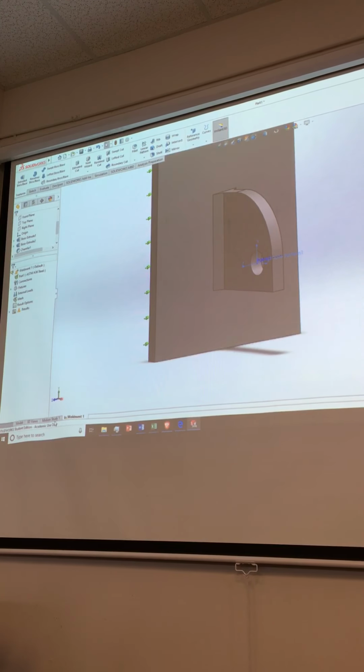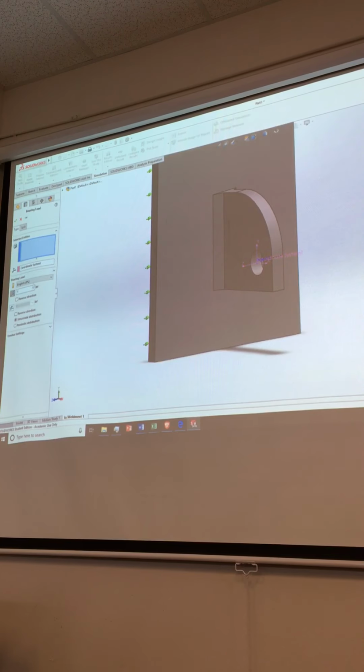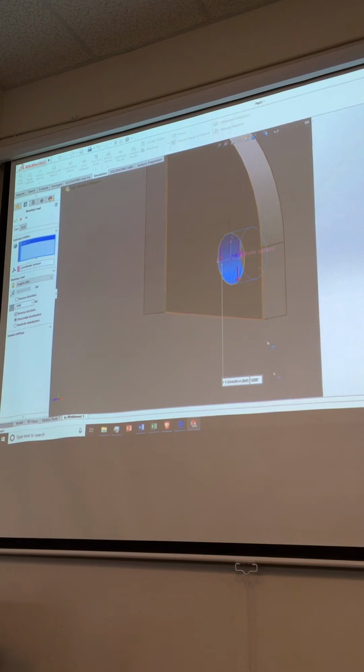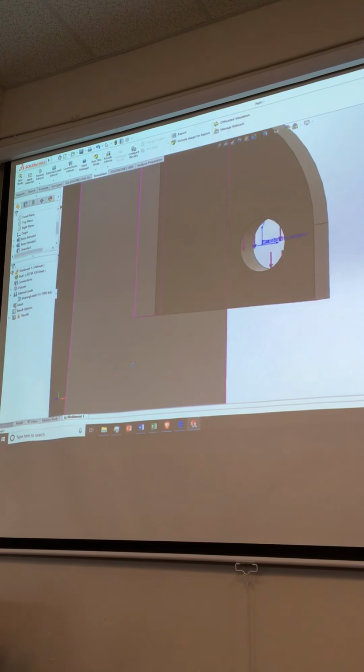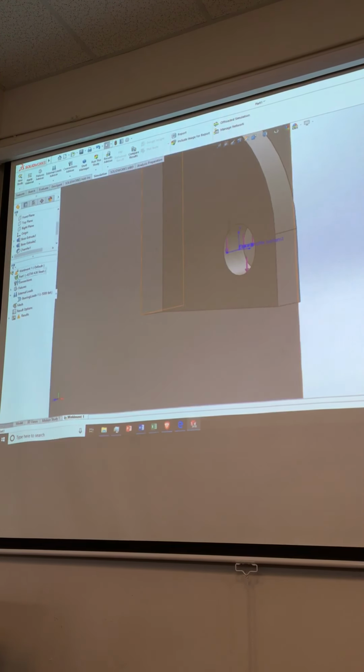So now we can go back to the simulation, right? And we can go do our external loads and put the bearing load on there. It even has the coordinate system. I can pick that nice thing there. And I can say I want to do it in the y direction and not in the x direction, and I want to do 5,000 pounds. And it wants to go the other 5,000 pounds. I look at the arrows. Let's go on to going down, 5,000 pounds. Looks like that's what I got there. And so now I've got a nice load in there that's pushing down on the bottom, right, 5,000 pounds. And we can go ahead and run this again.